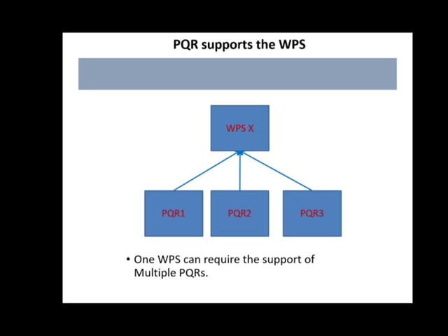And this can also pertain to post-weld heat treat or any number of essential variables. But a lot of times you'll look at a WPS and you're trying to do some work and not all the essential variables are addressed, so you have to go back and look at the other work and see what you can find. So that's how you can have multiple PQRs supporting one WPS.